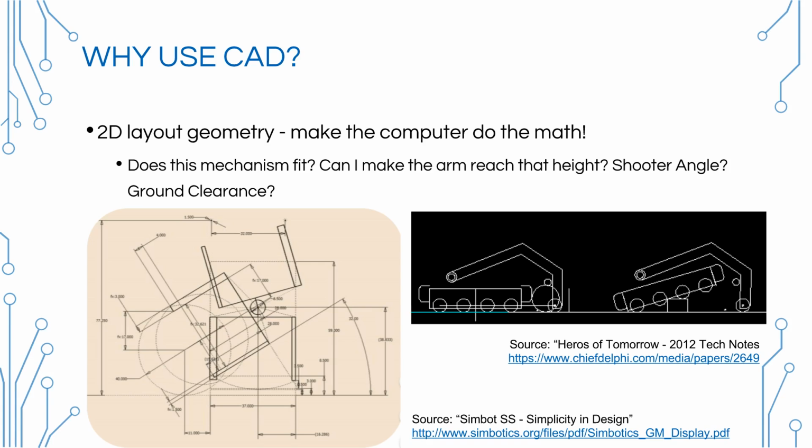for you. So if you look at the picture on the right with 67 Hot's arm, where they put those rollers and things to grab the ball and how it interfaces with the bumper, they're using tangency constraints there. That's something that just sketching it out, you're not going to be able to figure out exactly where it is. So you might be able to prototype that, but it'll help you get there a lot quicker if you just sketch it up in CAD and then figure out where those dimensions need to go.